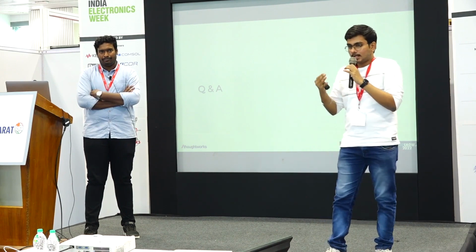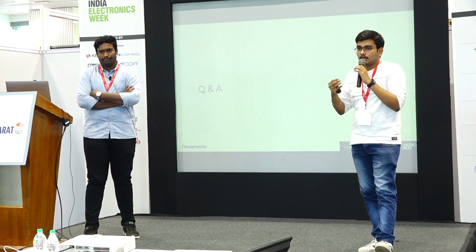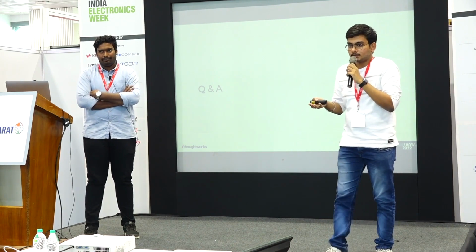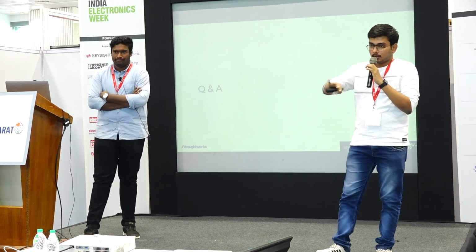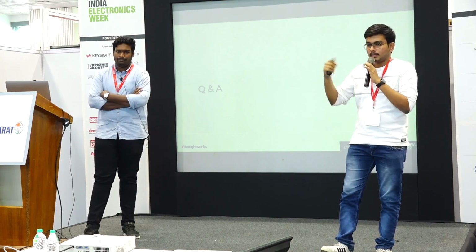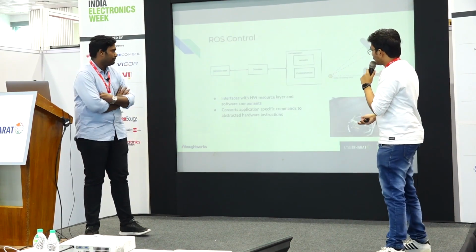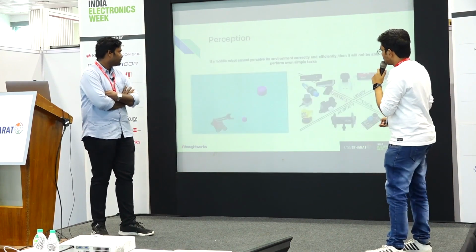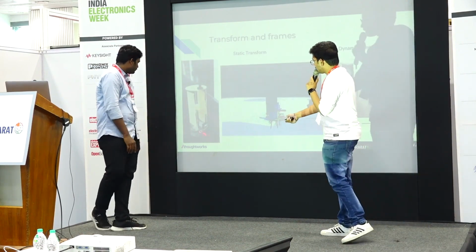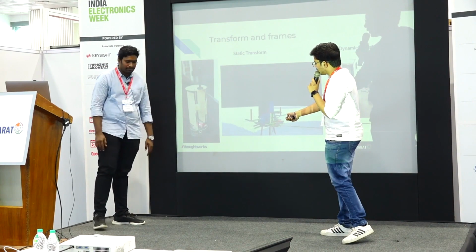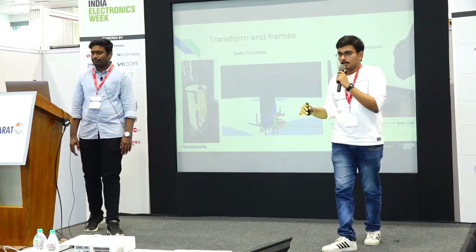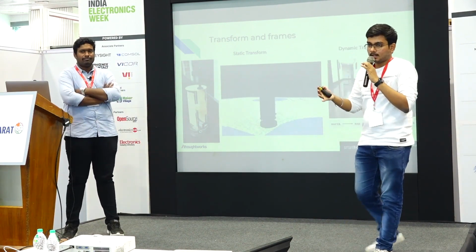Because the Raspberry Pi doesn't have that much signal strength, especially on the 5 gigahertz band, we went with a LAN cable. We just had a separate router on the bot itself, and we communicate through that. I think you can see here we have our separate router, and we transmitted data over that.